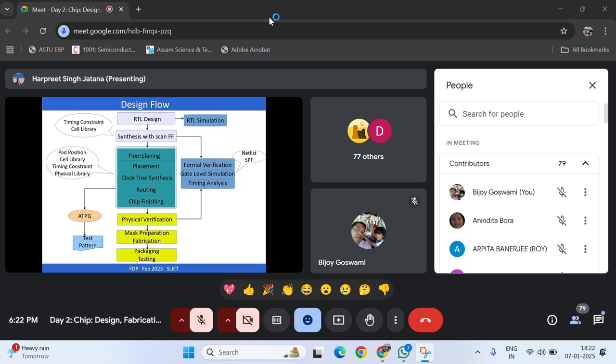So all these foundries will give you their standard cell libraries having more than 600, 700 different types of cells. You have to use those cell libraries, and the designer has to give timing constraints. Like if your design has to work at some 1 gigahertz kind of clock rate, that constraint the designer has to put in a software code. While doing the synthesis, it will choose those kind of cells so that those timings are met, and what kind of clock is coming from the input, all those things have to be given.